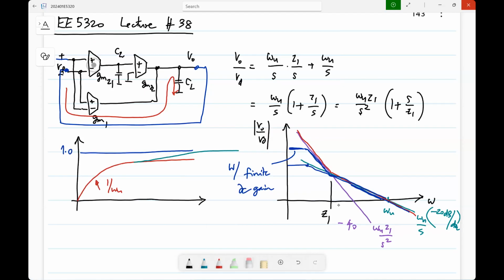Let's say that when you add this stage, the DC gain becomes 100. Okay, what will be the steady state error in that case? 0.01 roughly. Okay, so basically it will settle to 1 minus 0.01, but very slowly. It depends on how fast this stage picks up. So you don't want to make this very slow either. I think we have discussed this before. You please refer back to it.